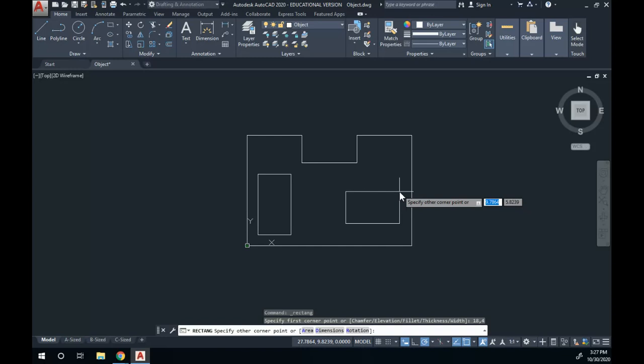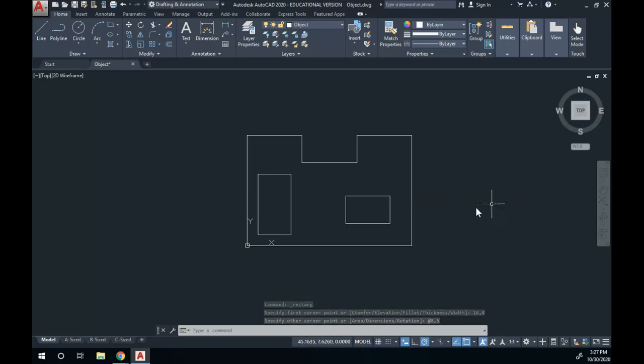So all I have to do is hit 8 for the x. How far in the x direction do I want it? How far in the y direction do I want it? Hit enter, and then it will create the rectangle as shown in 2-27. My first instinct was going back to the original point. If I reference it from the origin, I have to come out all the way and then come up. That's where I was doing the math. But AutoCAD does not do that. AutoCAD only references the origin for that first point. The second point, or the other corner opposite the corner you just placed, is always a reference to the first point. So my mistake.